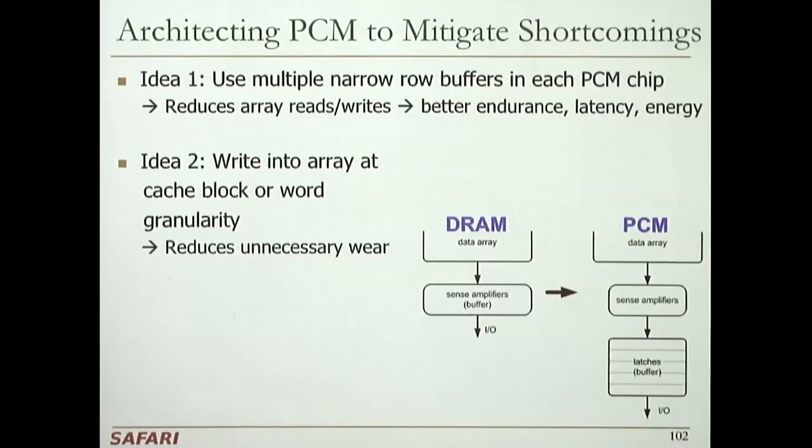The second step is you don't want to read from it either. So you want to do really good caching. Sorry, that's a joke, of course, but you want to reduce the reads, because reads are also slow, right? And their energy is high. So it's not a good enough technology to replace DRAM perfectly. So you really want to do some system-level stuff around it. And the stuff is really caching or reorganization of the device such that you do better caching and minimizing the writes.